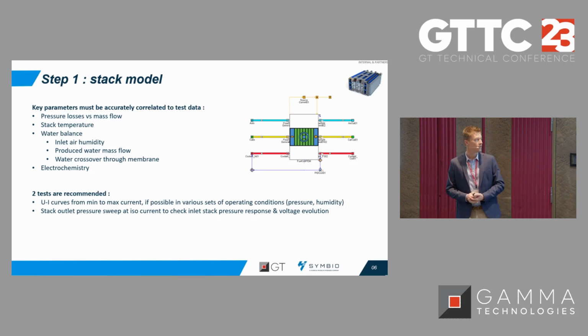The second recommended test is a pressure sweep out of the stack, specifically for this turbocharger integration, because the turbine at the exhaust will vary the exhaust pressure a lot, and you need to have a stack model with the pressure loss very well correlated to test data to have a good prediction behavior.